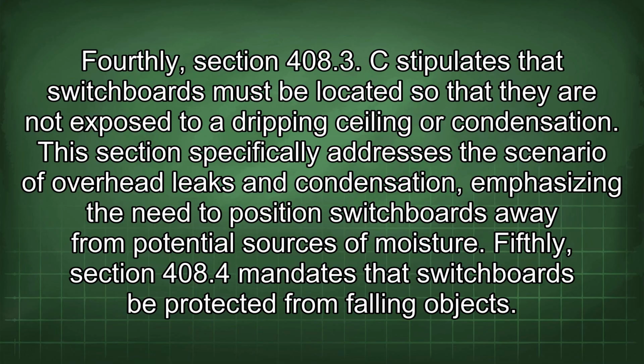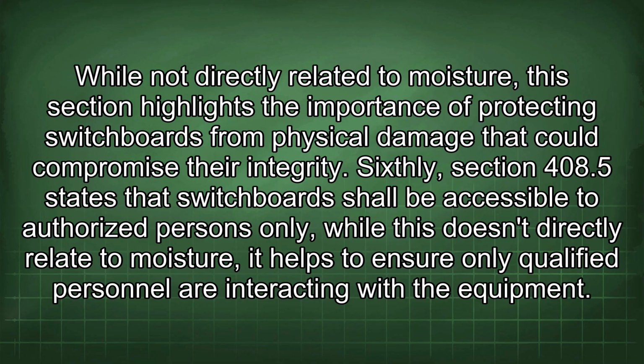Fifthly, Section 408.4 mandates that switchboards be protected from falling objects. While not directly related to moisture, this section highlights the importance of protecting switchboards from physical damage that could compromise their integrity. Sixthly, Section 408.5 states that switchboards shall be accessible to authorized persons only. While this doesn't directly relate to moisture, it helps to ensure only qualified personnel are interacting with the equipment.